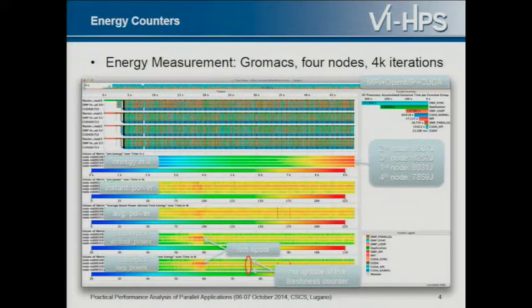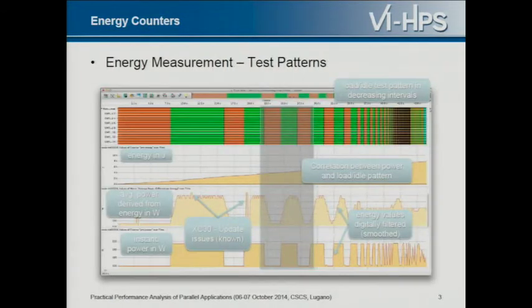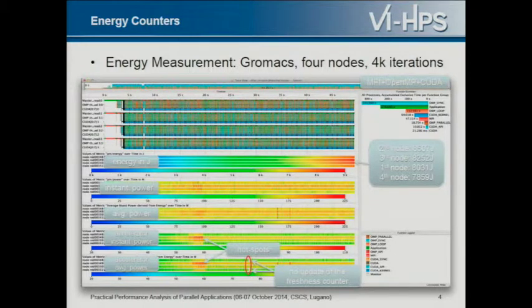To do that, we can utilize another feature of Vampir, which is called customized metrics. In almost every display which supports generic metrics, like the performance radar or the counter data timeline, you can right click, and instead of selecting the metric, you can use customized metrics, which will give you a nice graphical interface to click together other metrics that are available, like counters, like function runtimes, and operations like add, multiply, log, sinus, and so forth.